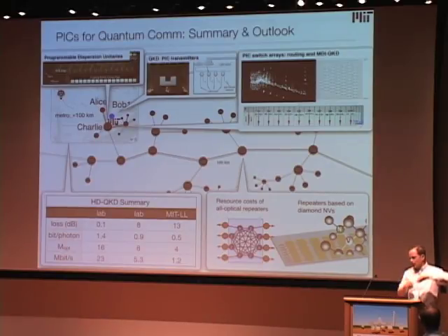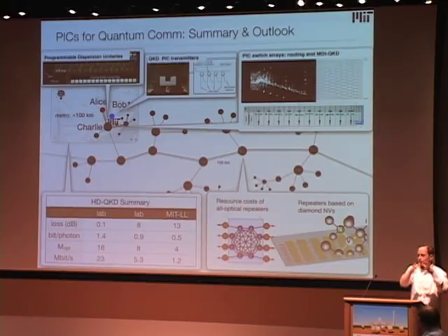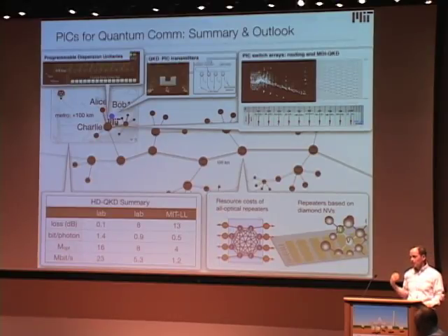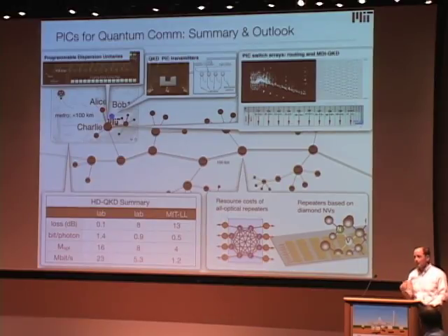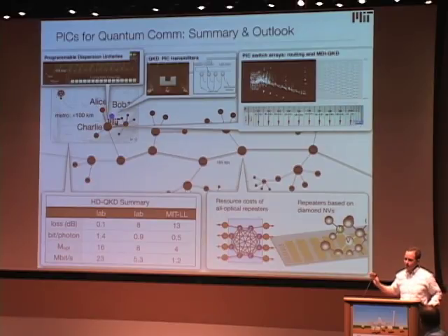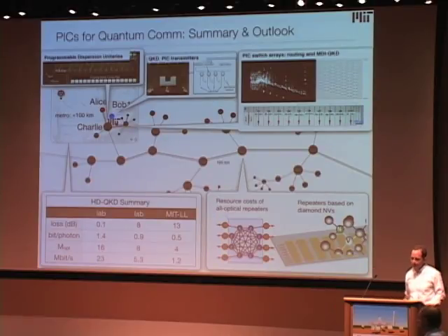Also, some recent work out of the University of Colorado showed that even for vertical couplers, you can get about 98% or so coupling efficiency, even in practice, by optimizing the grating design so that the coupled mode is very close to a Gaussian and therefore overlaps well with the fiber. So the numbers we showed are actually a little bit conservative, because we assumed we wanted to couple to many, many modes. In our chips at the moment, we get maybe 2 dB of coupling losses, but I think very soon you should be able to go well under 1 dB, and people are beginning to do that as well.